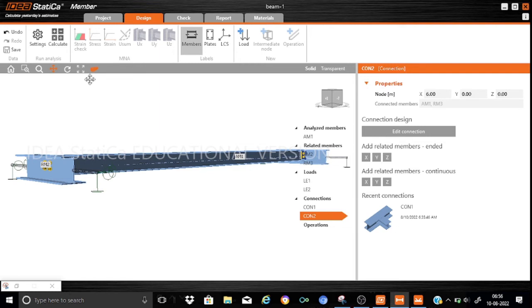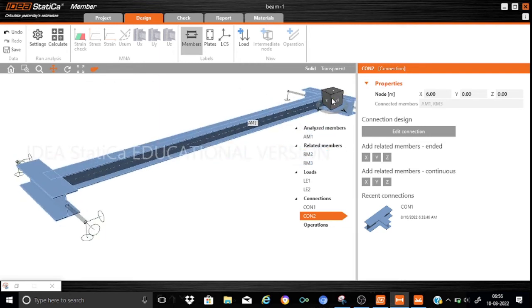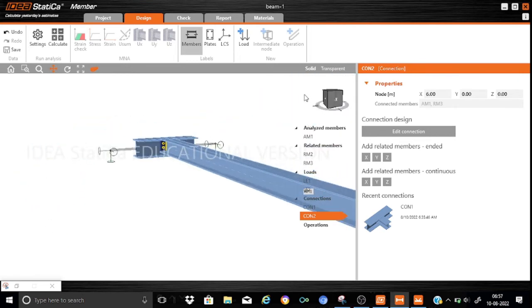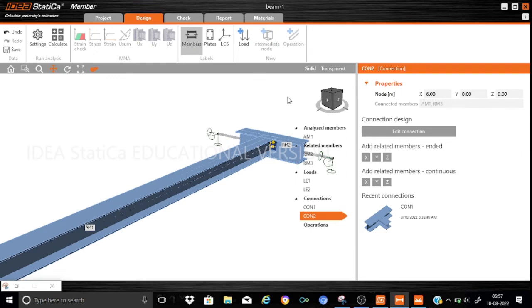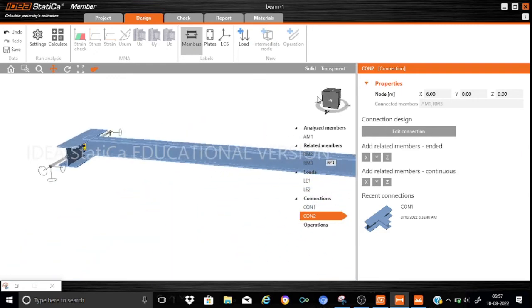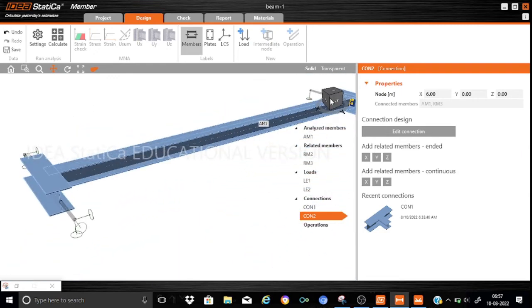One very important thing I want to tell you is that the beam we are considering is a laterally restrained beam. Laterally restrained beam means that we have some mechanism to control or restrain the out-of-plane translation of the compression flange. And this mechanism we used to provide when I was working in the industry.